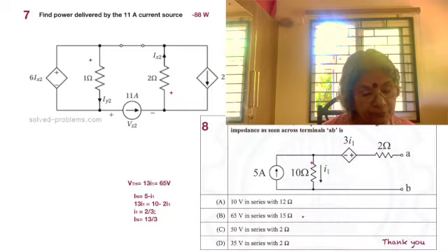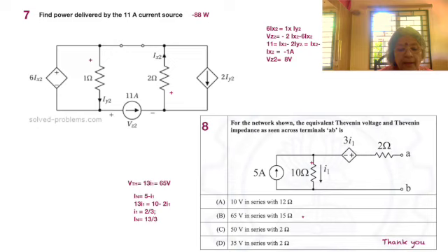But at the same time, let's try to find the Norton's current also, and get the ratio to obtain the Thevenin's impedance, because we may get such problems. Let's short AB, and now the Norton's current is equal to whatever flows. There's a current coming from the 5 ampere source. I1 flows out of it. The rest will flow as the current through the 3 I1 source, as that's a voltage source, so the current and voltage can be different. Then it flows through the 2 ohms and to the short circuit as the Norton's current. So 5 minus I1 is going to be the Norton's current.